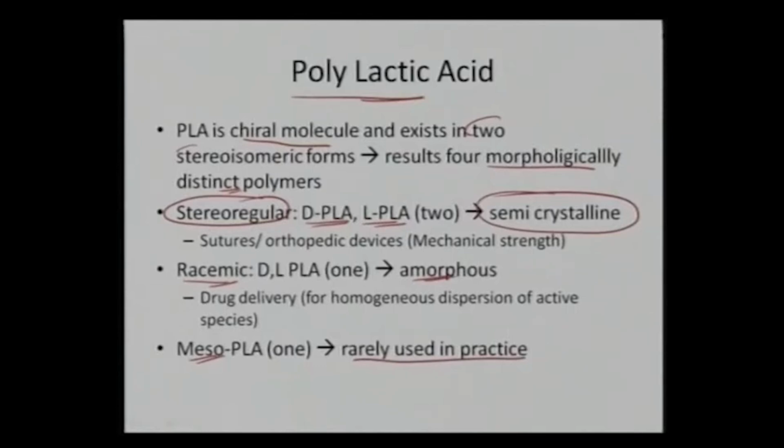Now coming to their overall properties, since the stereoregular DPLA and LPLA are semi-crystalline in nature, they have good mechanical strength, and because of this good mechanical strength, they are utilized in sutures or orthopedic devices. On the other hand, D,L-PLA is amorphous in nature, so it can be utilized as a medium for dispersing active species or drugs for drug delivery.